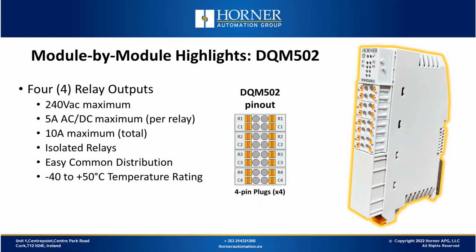The next module we're looking at is a relay output only module. This has 4 relays and does not have any digital inputs. What makes this module different is the fact that it has more solid relays. So there's a higher current capacity per relay and a higher current total capacity for the entire module.